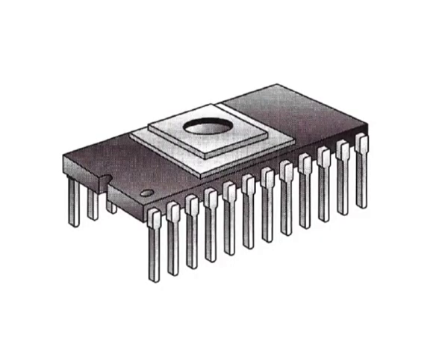UV EPROMs. You can recognize the UV EPROM device by the transparent quartz lid on the package as shown in the figure. The isolated gate in the FET of an ultraviolet EPROM is floating within an oxide insulating material. The programming process causes electrons to be moved to the floating gate.